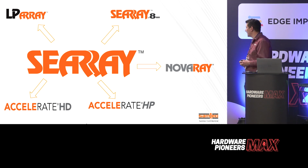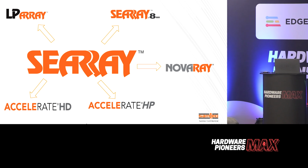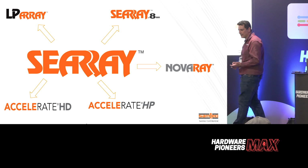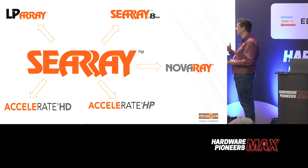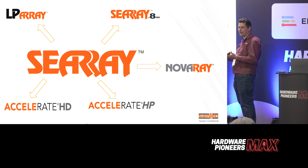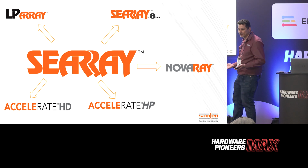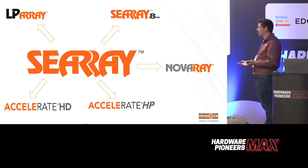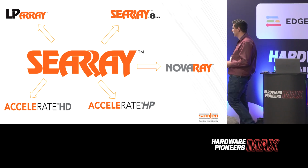From there, we started to develop based on customer feedback. They said, okay, we need a higher density connector. C-Ray is 1.27, so we moved into a 0.8 solution, almost half the size of the original C-Ray, to suit different applications. Then we had customers saying 7 millimeters is too high for us, we need something smaller. We developed the low profile array, which is 4 millimeter stacking height. Again, this is also used in the FPGA ecosystem for RF SOCs. It's what Xilinx calls the RFMC connector, which is based on the low profile array.